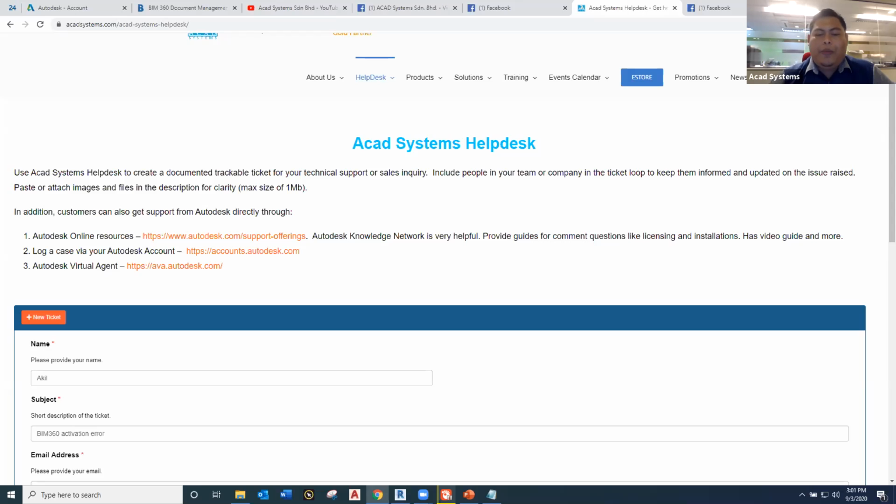But Navisworks Manage BIM 360 is different. In Navisworks you can run clash detection, but by working in Navisworks Manage BIM 360, you are accessing the coordination model in BIM 360. We call it the BIM 360 Coordinate package. You are accessing the model and running clash detection from the cloud models uploaded on BIM 360. So that is the difference between what I showed earlier and Navisworks Manage BIM 360.